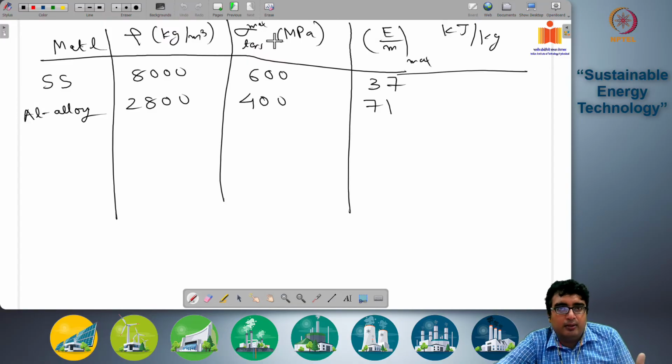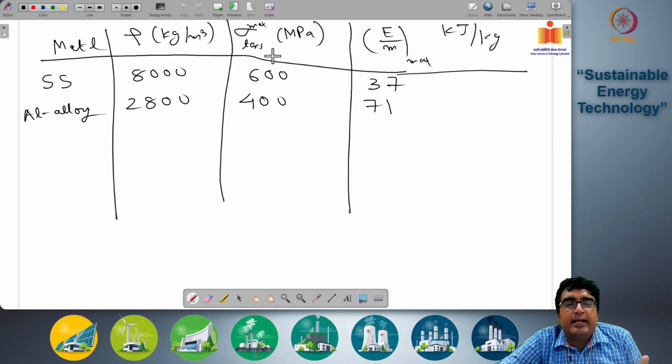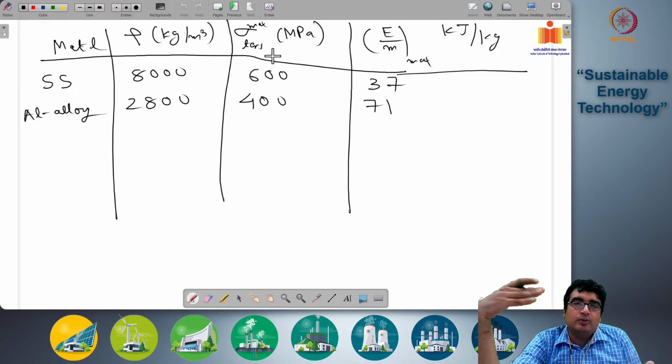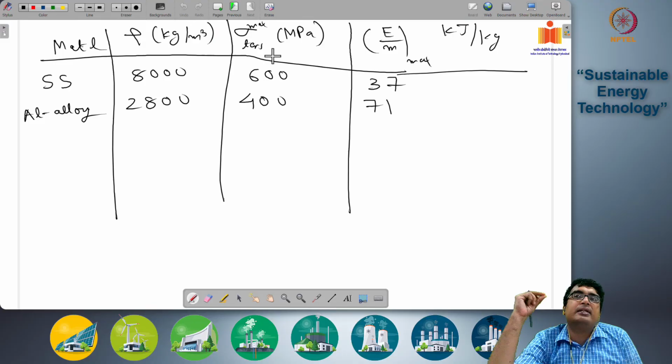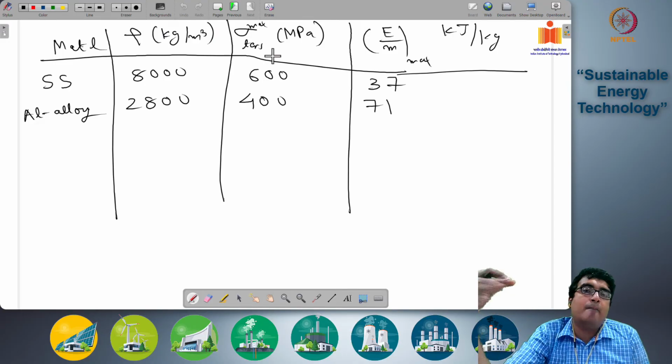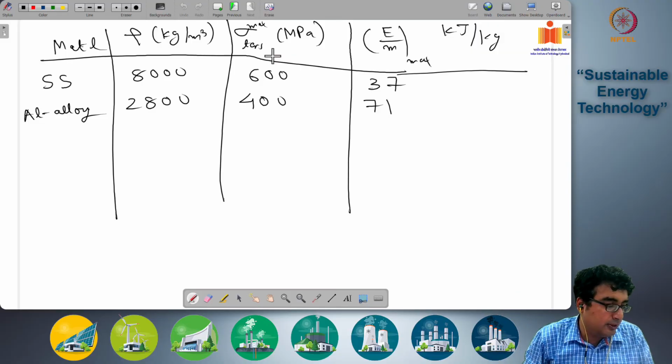So if you look at 200 kilojoules per kg, and for example kilojoules per meter cube, if you look at the case for storing water, there you are getting significantly more amount of energy per meter cube. So you are getting much lower energy densities in a flywheel system compared to pumped hydro system. So that comparison you can also make for these kinds of systems.